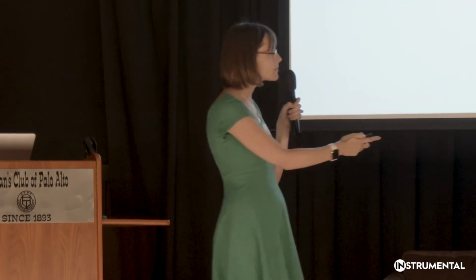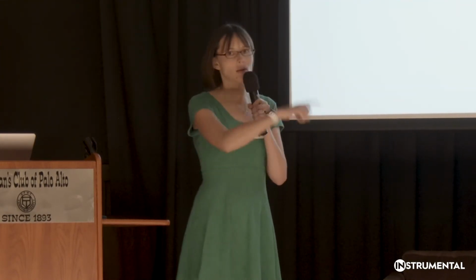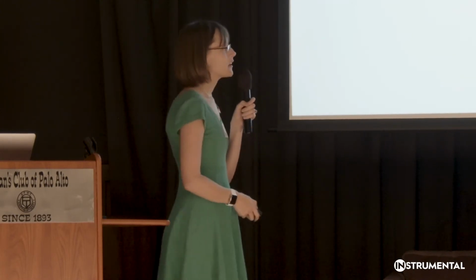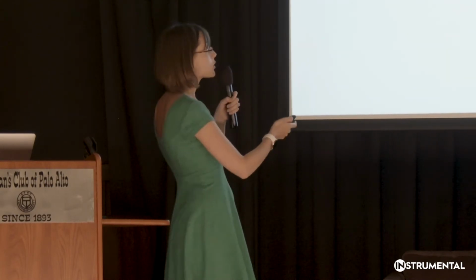The root cause of this was actually the part did not match the CAD. So they had built the tool wrong. And he was able to find this within the first day of the EBT build, the first build, so before they'd replicated the tools. So it's a big savings for him. He found this issue. They were able to get parts before the end of the build, so they were able to validate, happy ending, and they were able to do so without essentially replicating a tool that had an issue.